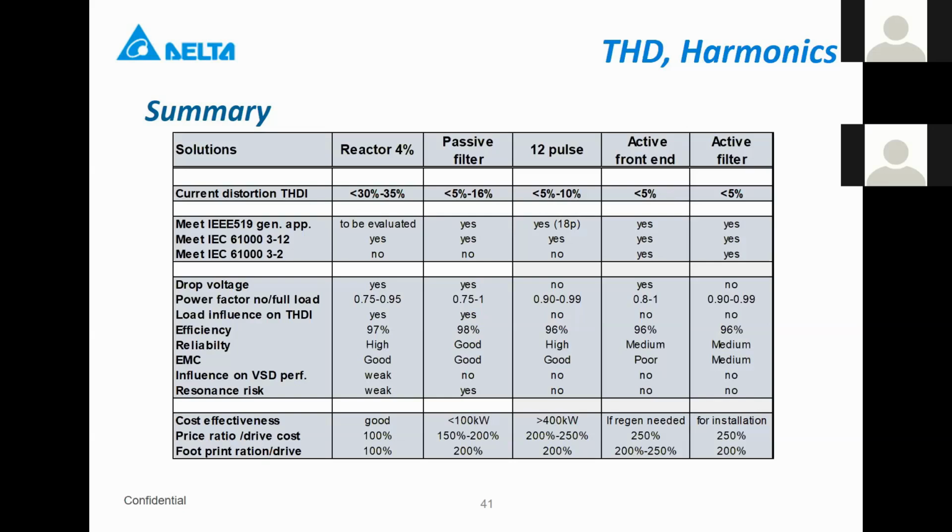At this moment, it's going up already to 160, 200 kilowatts, then it's cost effective. There is a point, of course, that is very important: because we are using capacitance and inductance, you always have a risk of resonance if you use a lot of these kinds of filters in one system.